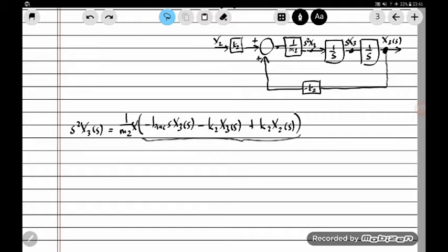We've already got the signal sx3 defined in our diagram, so we can branch it off from here and multiply it by minus b increment and just add it to the summing block. And that completes the diagram for our second equation.